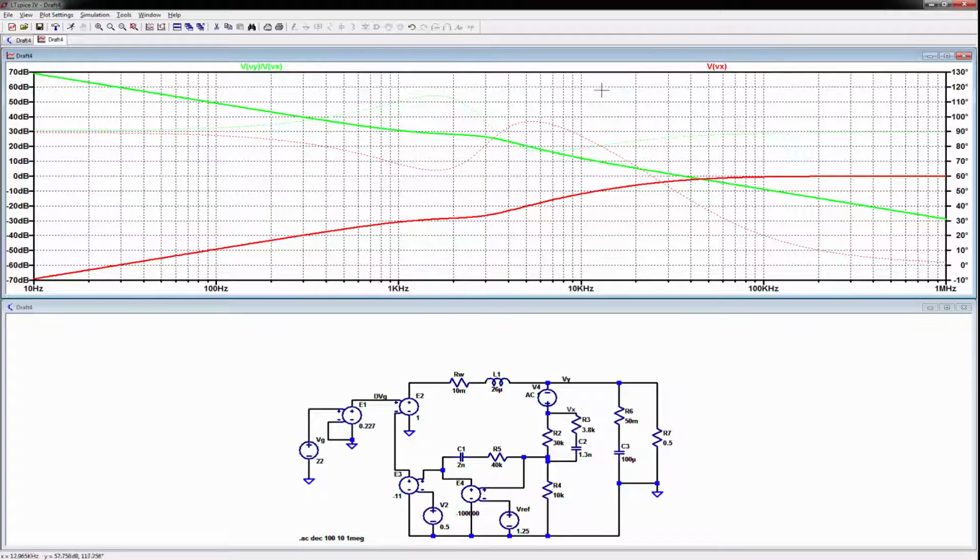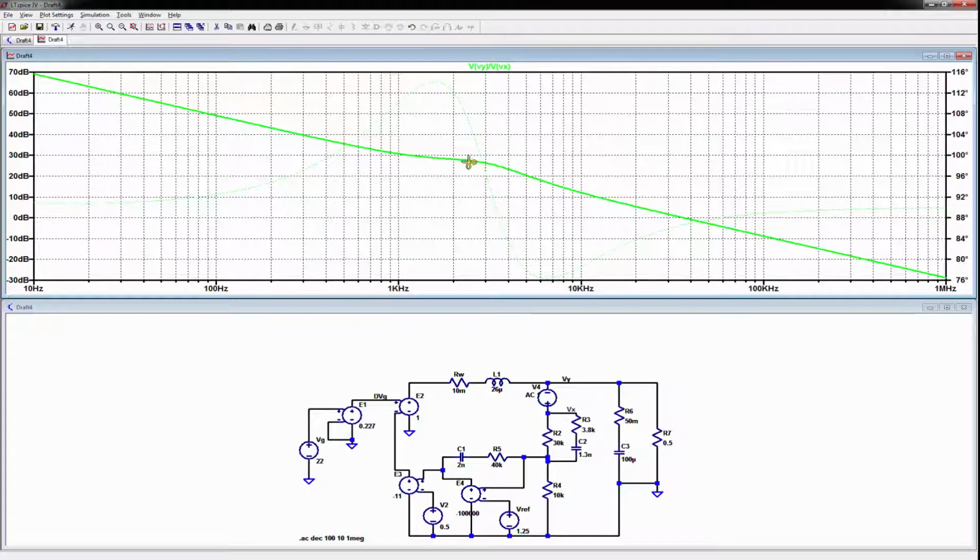So now what I just did is I need a Vy over Vx, okay? I need a Vy to Vx. So you just can't grab here to here, because then it's Vy minus Vx. I don't want a Vy minus Vx. I want a Vy over Vx. So I plot a Vy, I plot a Vx, and then I copy one and put a Vy over Vx, and that's the one we want. So I get rid of this there, and there's my phase gain.